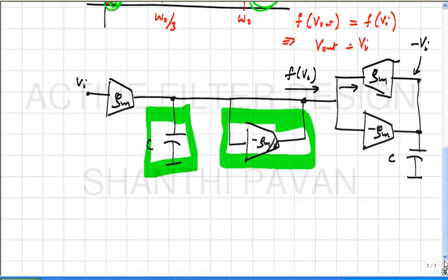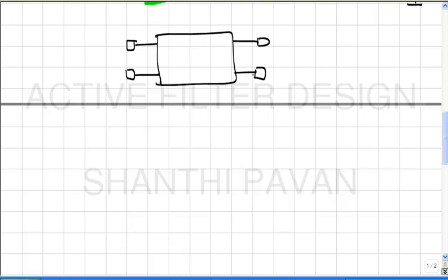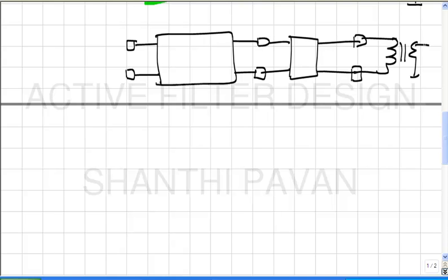One aspect of measuring distortion is the following. As we discussed a while back when we were testing a filter, right? It's not that we have access to just the filter, but this is sitting inside a chip, and then you need to put a buffer kind of thing, and then there's a balloon, and then there's a cable going all the way to the test equipment. So one thing about distortion measurement, where again you could get conned, is the fact that this whole test setup will generally have some frequency response, correct? So even let's say the fundamental has some strength here and the third harmonic has some strength here, right? What you're measuring is the fundamental strength here and the third harmonic strength there, right?